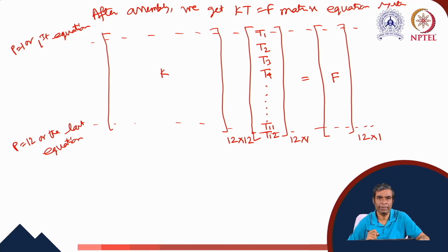Now we already know that from the heat diffusion problem, the global matrix will be symmetric, diagonal dominant, and a positive definite matrix. So this matrix can be conveniently solved using the direct methods or by using the iterative methods. So this completes the discussion of the construction of ID and LM arrays for a single degree of freedom in 2 dimensions. This can be extended for triangular elements or also for the higher order quadratic elements in 2 dimensions.